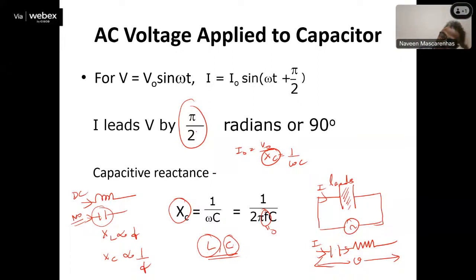Once the capacitor is fully charged, the current through the capacitor is always 0, right? In DC circuits, it doesn't allow DC to pass through. There is no current. So coil says yes to DC, but capacitor says no to DC. Coil says I'll oppose low frequencies less and high frequencies more, but the capacitor says I will oppose low frequencies more than the high frequencies.